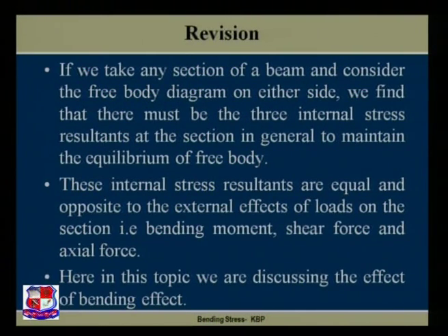Let us revise what is bending stress. If we take any section of a beam and consider the free body diagram of either side, we find that there must be three internal resisting components generated because of the application of the external forces. These three internal resisting components are bending moment, shear force and axial force. So the topic we are discussing is the effect of bending.